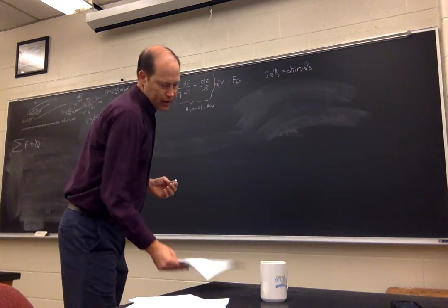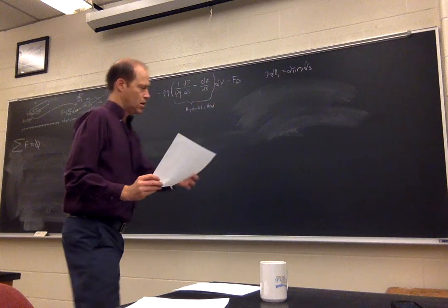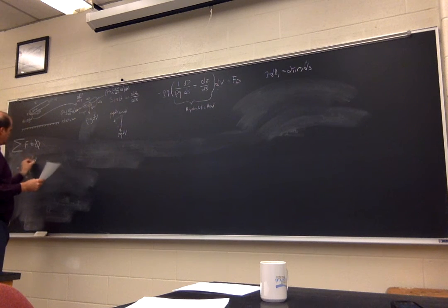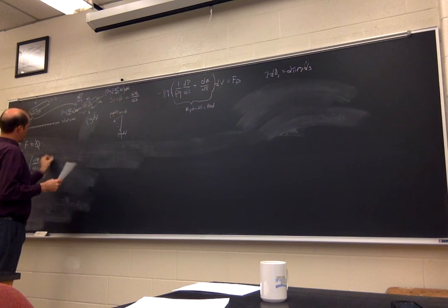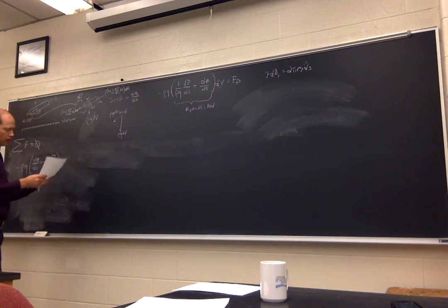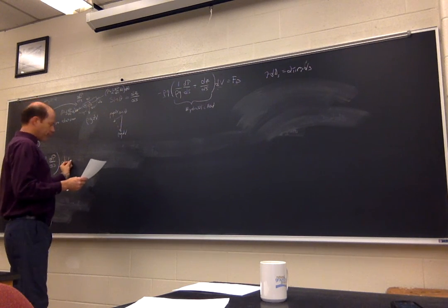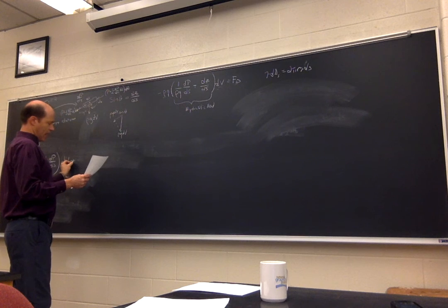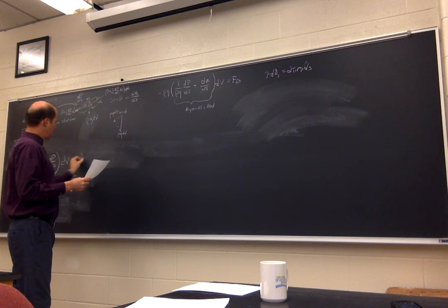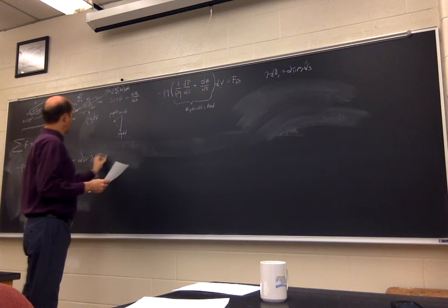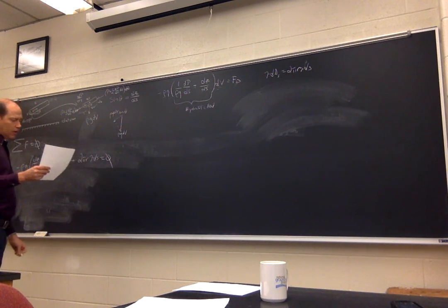Adding these two forces, on the driving side we have minus rho g dz/ds plus 1 over rho g dp/ds, which is our hydraulic head, times dV. Then we add our frictional force, 2 pi r tau ds, and the sum of those must equal 0.